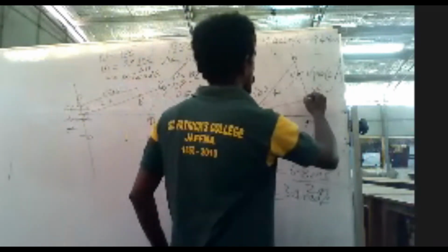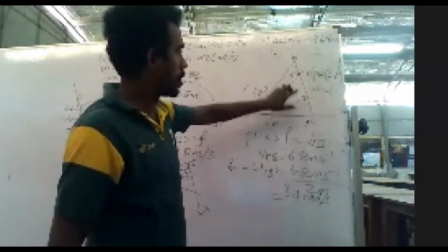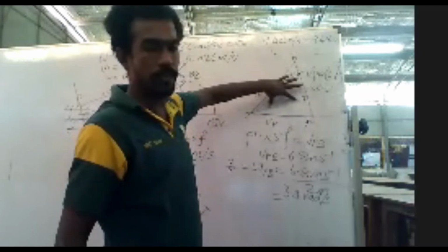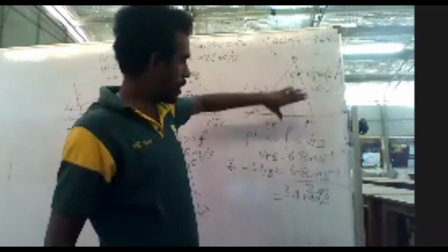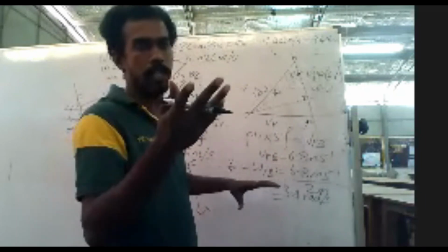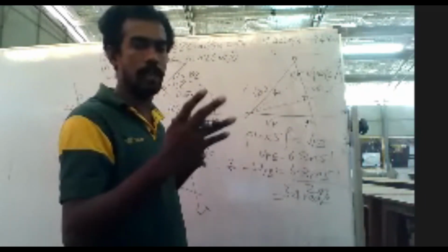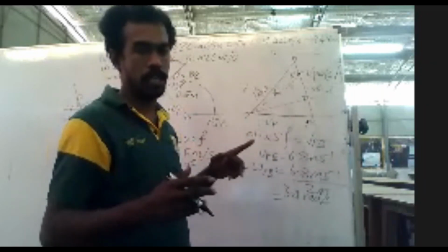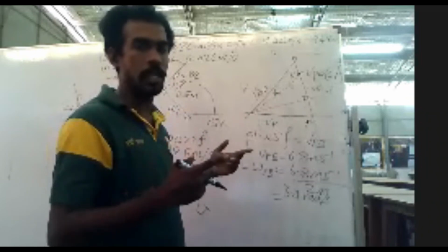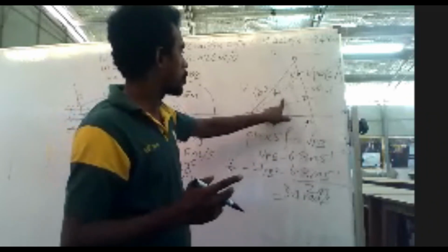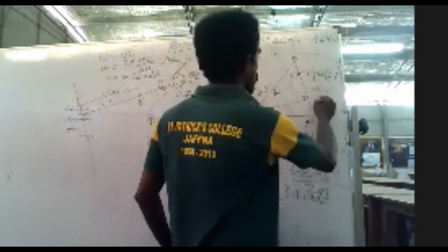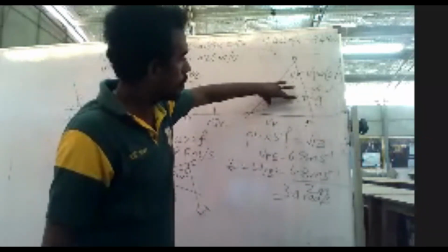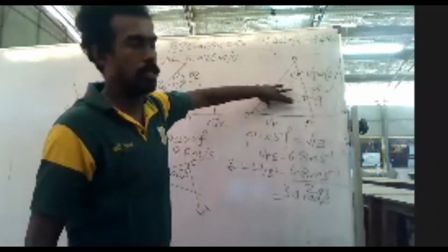For your understanding, you need to do that because a small difference in the angle will have a big effect on the length. When you multiply it with your scale factor, that will be magnified, and your final answer would be very different from the expected answer. So when you are marking the angles, be very specific. So this is my perpendicular, and this should be the minimum length.